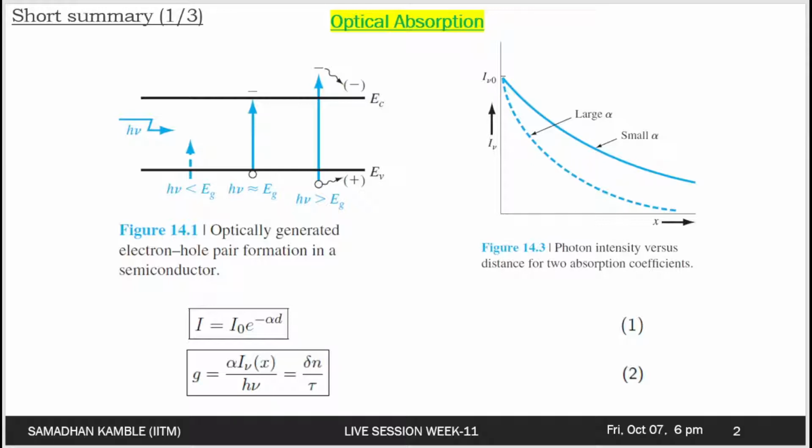Okay, good. So as I was mentioning, if the photon energy is less than the band gap energy, the photons are not readily absorbed, and in this case the light is transmitted through the material, and the material appears to be transparent. If the energy, that is h nu or h cross omega, is more than the band gap energy, the photon can interact with a valence electron and elevate the electron from the valence band into the conduction band.